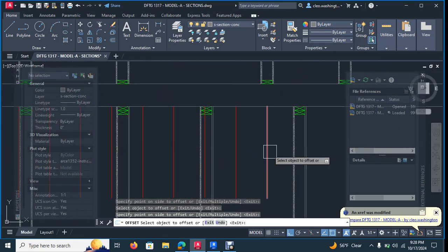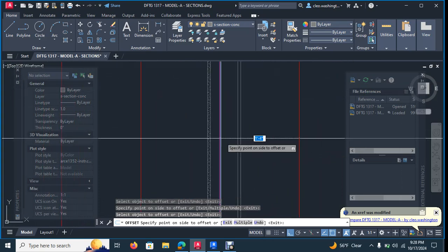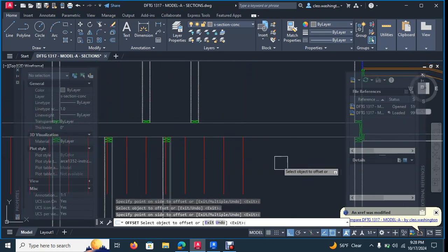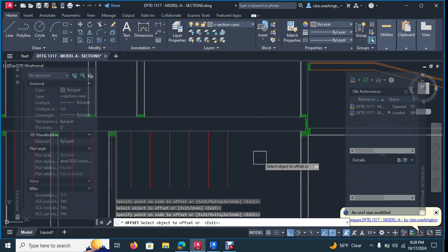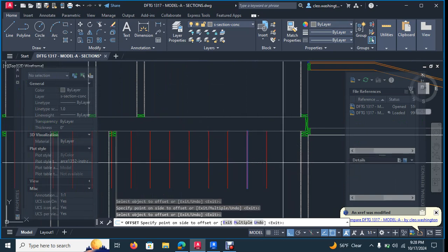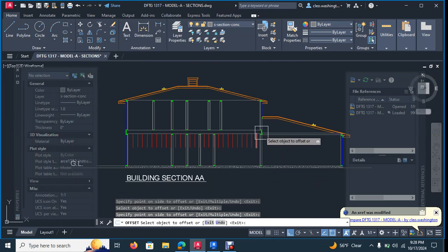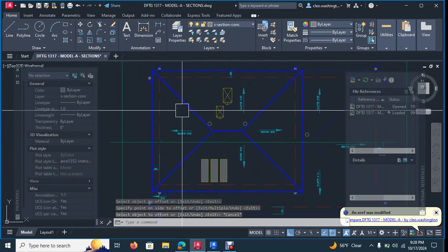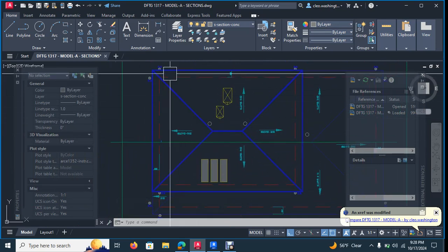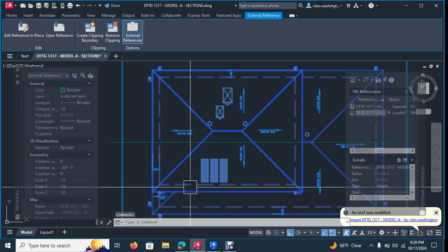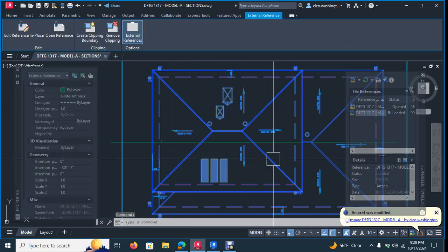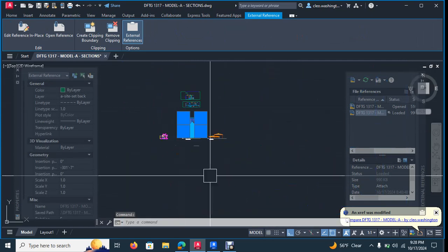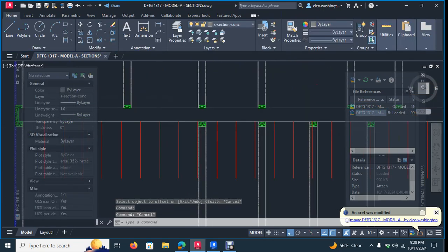You guys are going to see what we're doing with this. Okay, we're getting ready to place the floor joists because they are spanning the shortest distance, and the shortest distance appears to be plan north and plan south. Okay, think if you're framing up the floor here, you're going to span from here to here. You wouldn't go from here all the way across, because north and south is the shortest distance here, not east and west. Okay.